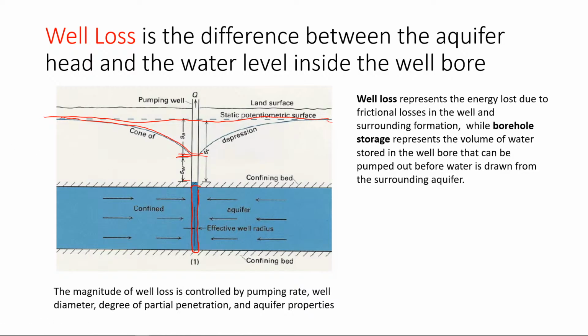So this could cause this well loss here. That's called well loss, and this well loss is also a function of several things. It's a function of your pumping rate, your well diameter, whether you are fully penetrating or partially penetrating. So all these things would be factors that will determine your well loss.